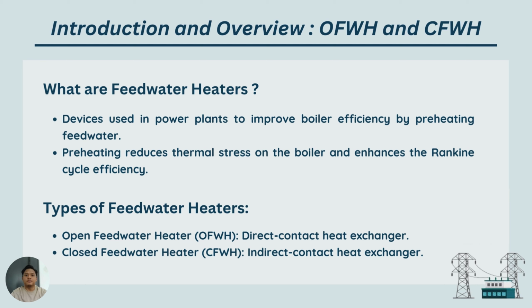thermal power plants. So, feedwater heaters serve as critical components in a power plant by preheating the water before it enters the boiler. They reduce the energy required to convert water into steam. This improvement in thermal efficiency lowers fuel consumption and also operating costs.